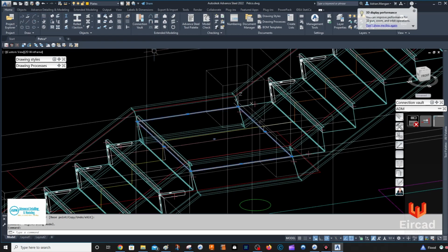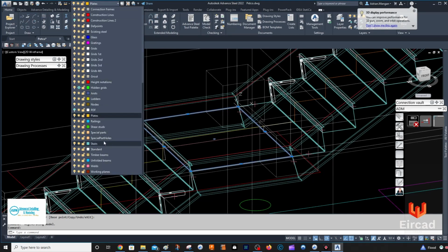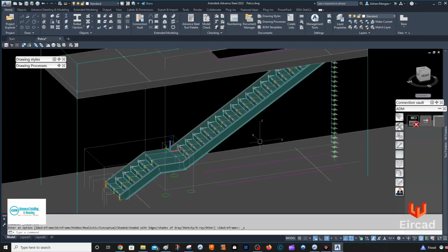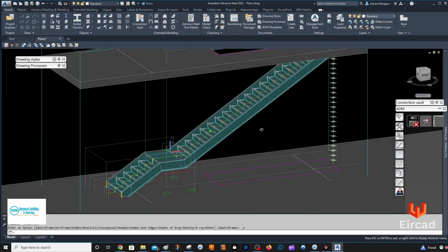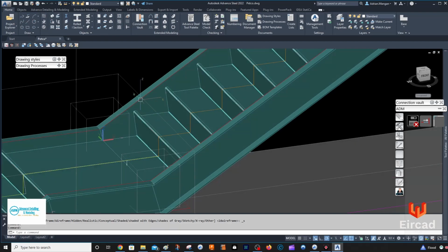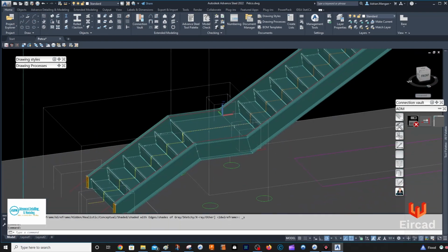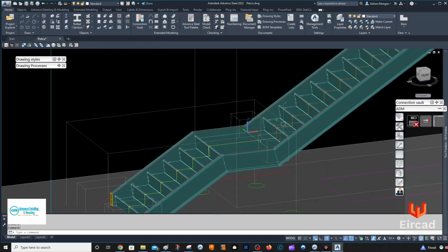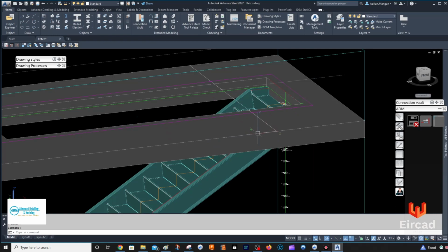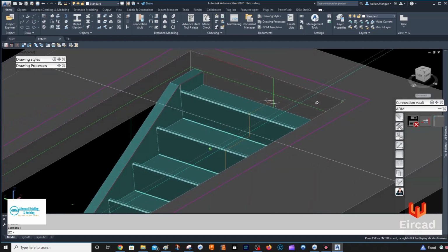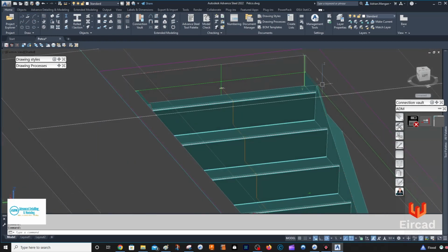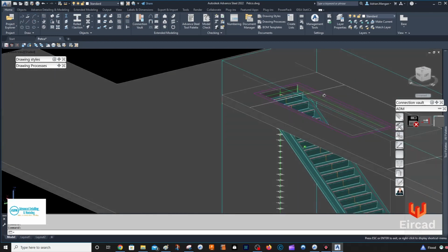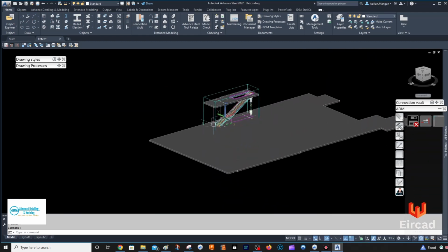And now if you want to select the plate and put it on the stairs, it's the same color, and you can go to your 3D view, shaded, and you're getting your stairs. I will also model in a piece of concrete here. Yes, a little crazy probably, but I will model in a piece of concrete for if I want to bring this over to Fusion, then I won't have to model it in over there. So you can see my opening is not quite big enough, or I'm not centered, so I can fix that by just dragging the boxes across.